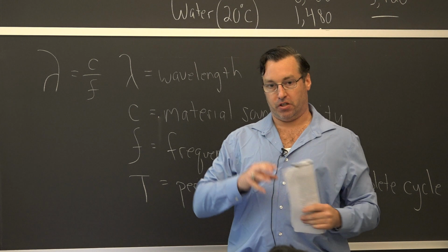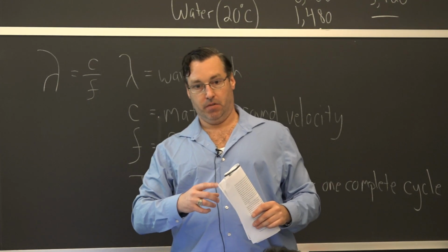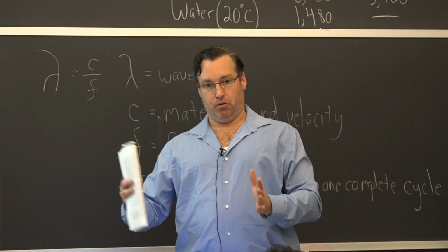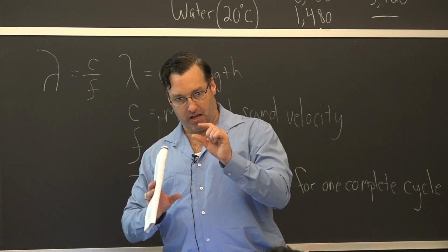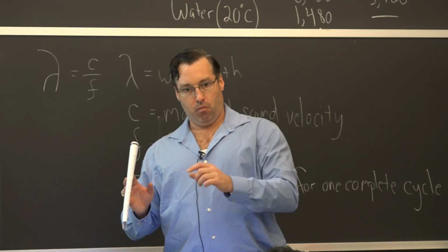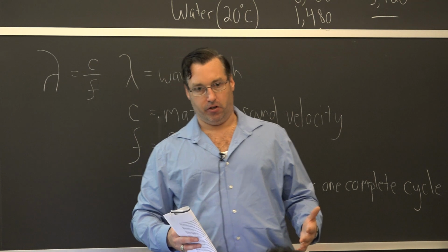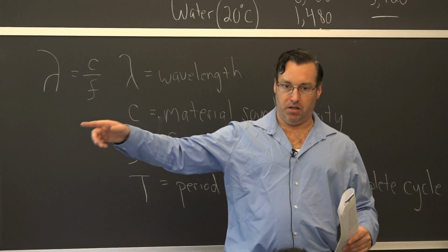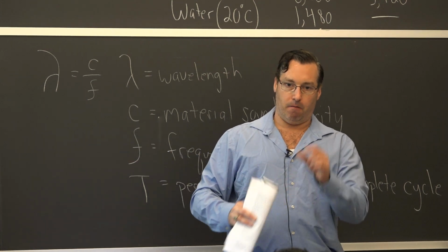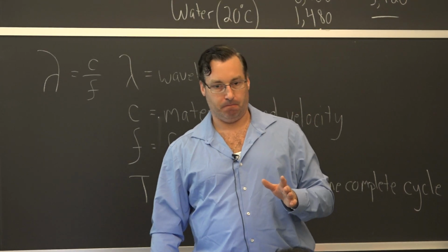But if you have an ultrasonically noisy material such as titanium or aluminum and it's a thick sample, you have to recognize that the resolution, the flaw size that you can detect, will be greater than if it was not an ultrasonically noisy material. So it's a trade-off between how deep you want to penetrate into the sample and how small a flaw size you are required to detect.